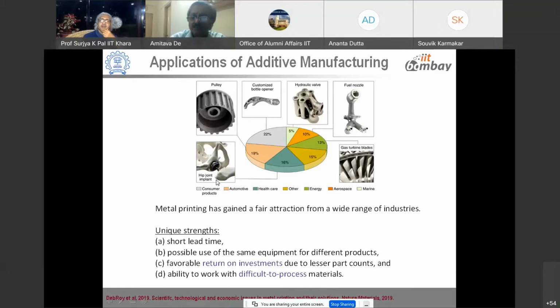the shape of the part itself shows that to cast such a part of a material which is very difficult to process, very difficult to melt otherwise and put in a mold, because the additive manufacturing process can work from a powder, and it can be prepared in a layer by layer manner, a free form can be produced. So that's why it is the attraction. Any fine shape can be produced, and it's everywhere.